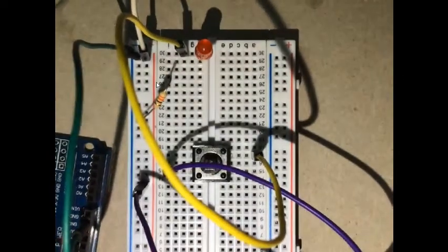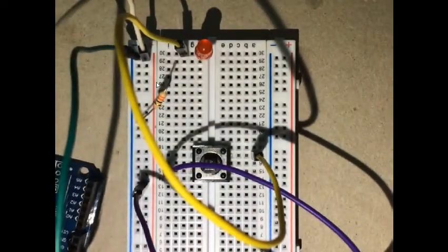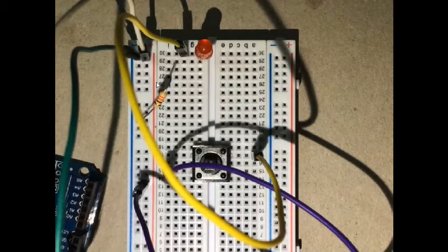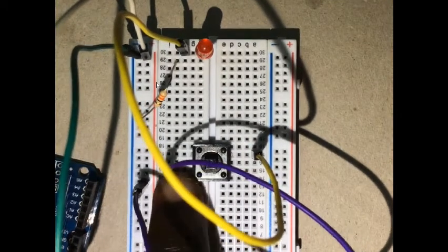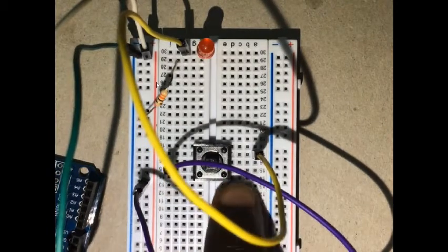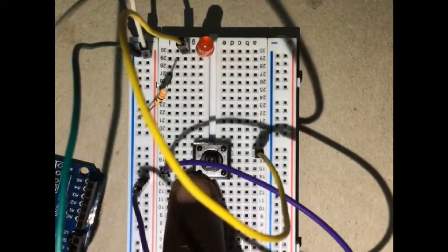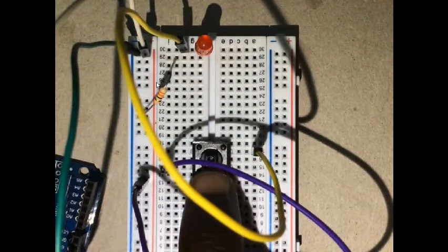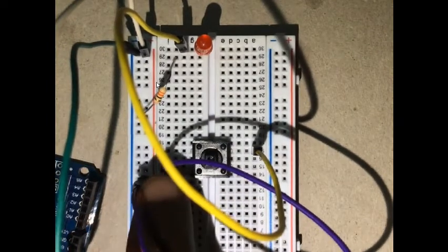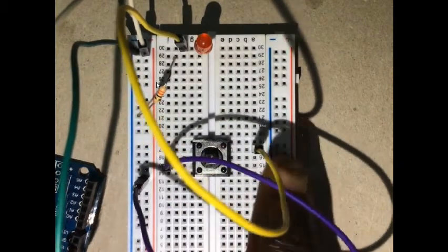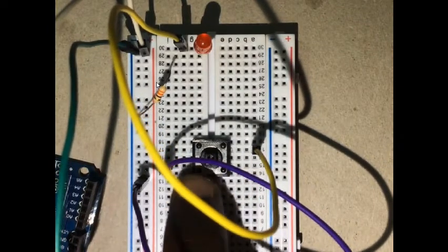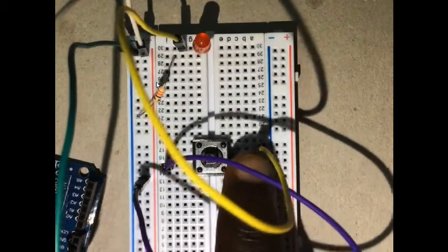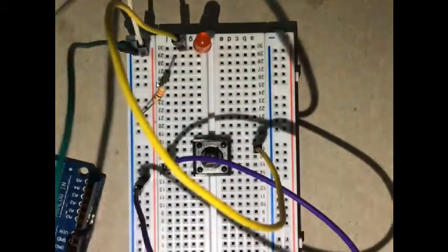Okay, as you can see the LED is not on. However, we said that anytime the button is pressed, what happens? All the leads of the button, so the 4 legs of the button, are electrically connected together inside the button, which means that this purple wire and this yellow wire will be electrically connected together, and that means that 5 volts will flow through to the anode of our LED and make it come on.